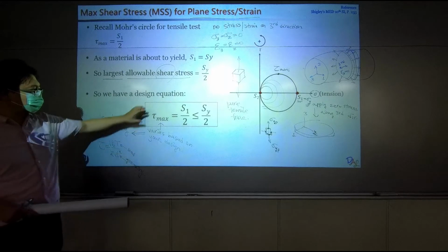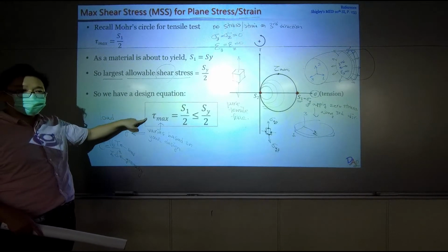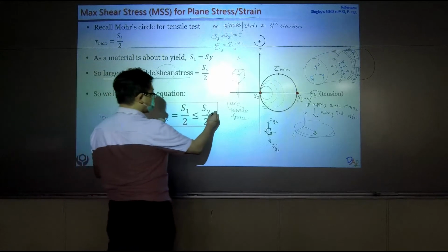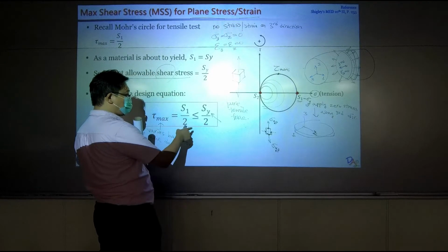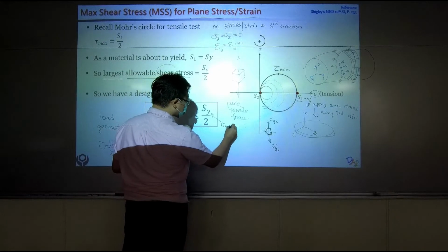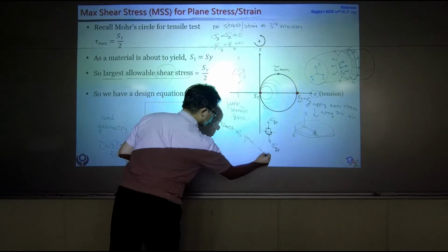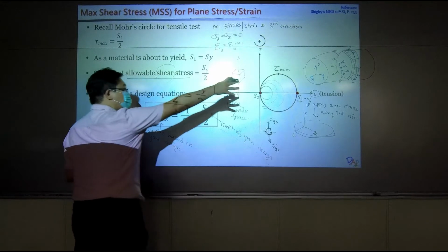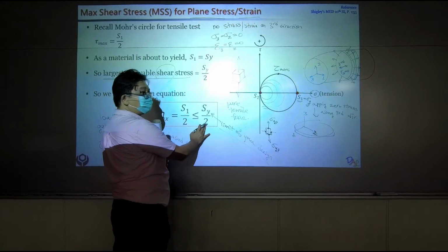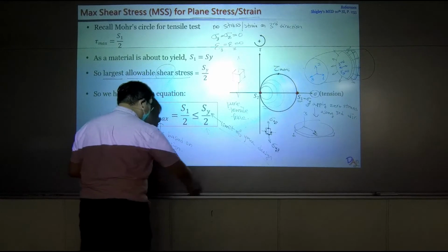After calculation, you need to determine what will be the maximum shear stress for your design. Then you will check whether it will be smaller than the limit of your material. So this is like a limit of your design. And this limit, based on what we described, will be half of your yielding strength. Okay, so this is related to material property.